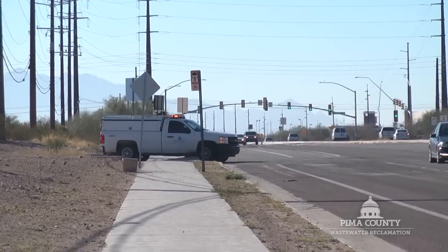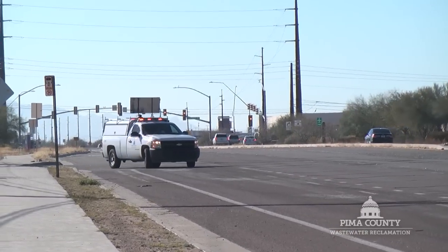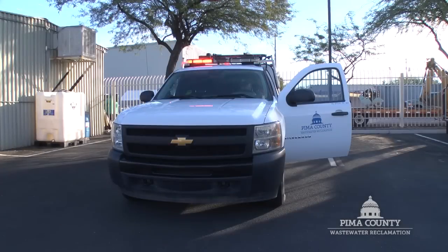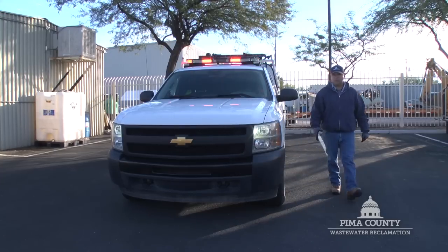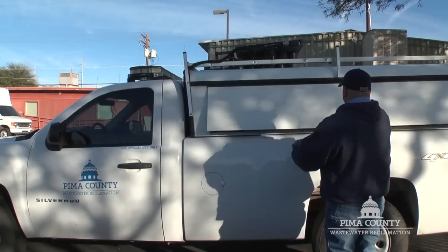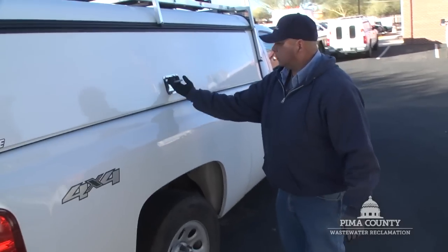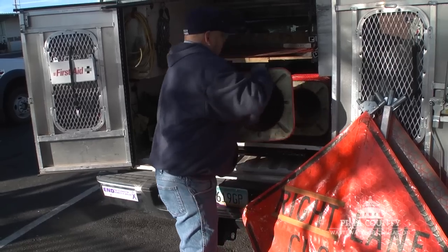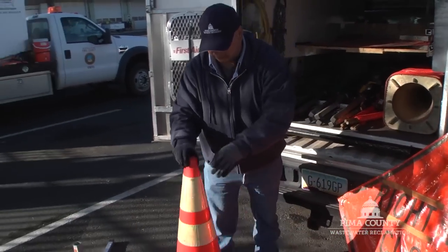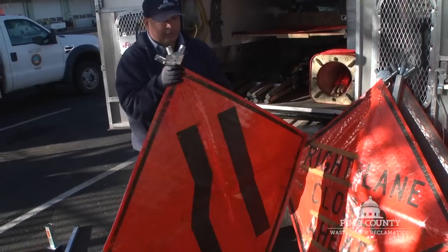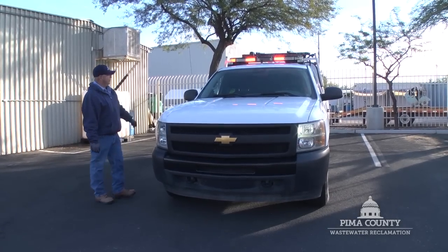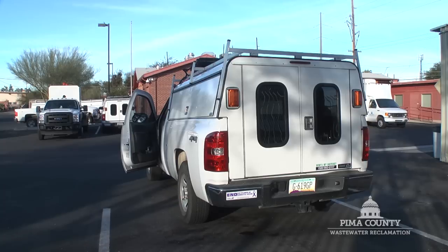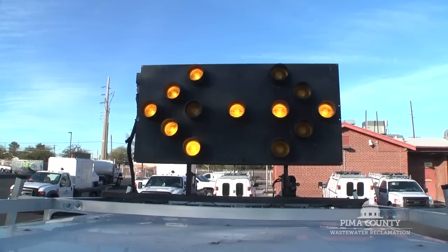A support vehicle is required for all high-hazard temporary traffic control zones. Before leaving the facility, a vehicle pre-inspection is required, as well as a post-inspection upon return. During a pre-trip inspection, you should inspect the vehicle, both internal and external, and visually inspect all traffic control devices, including cones, flags, and signs. Assure that the vehicle is equipped with appropriate safety lighting and all the equipment, including overhead lights and arrow boards, are working properly.